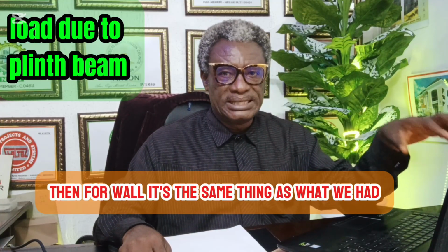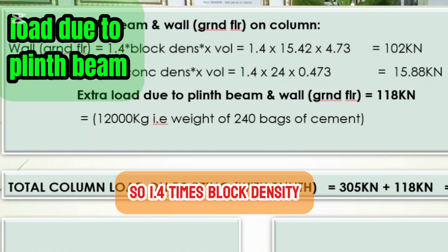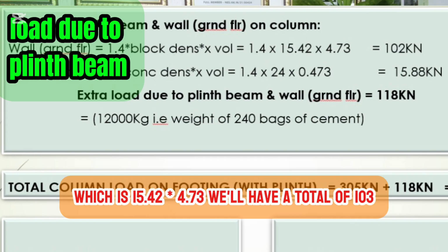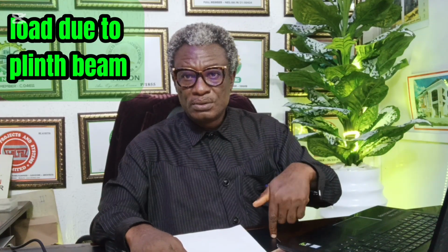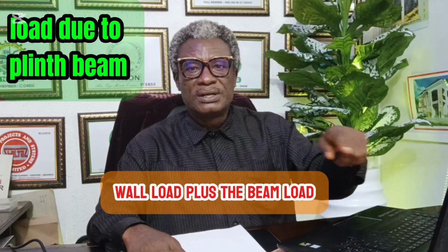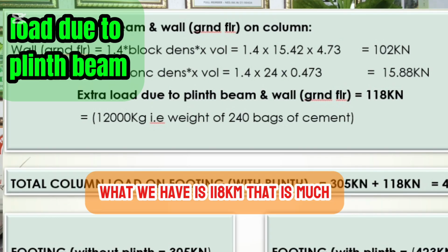15.88 kilonewtons. Then for the wall, it's the same thing as what we had. It's the same headroom and the same span. So 1.4 times block density, that's the specific weight of block, which is 15.42, times 4.73, we'll have a total of 102. So if you add the two together, that is the weight of the wall load plus the plinth beam load, that is 102 plus 15.88 kilonewtons, what we have is 118 kilonewtons.